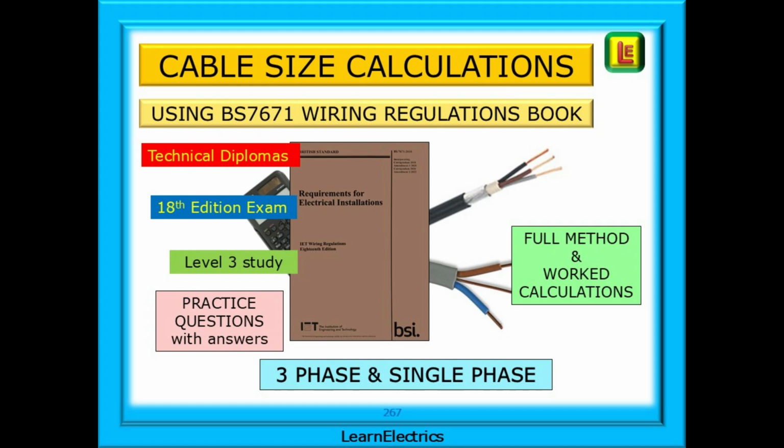In this Learn Electrics video, we will look at how we can make cable size calculations, how we can choose the correct breaker or fuse sizes, and how we can determine if the voltage drop in the cable is within limits just by using the wiring regulations book, nothing else. We will look at both single-phase and three-phase applications.